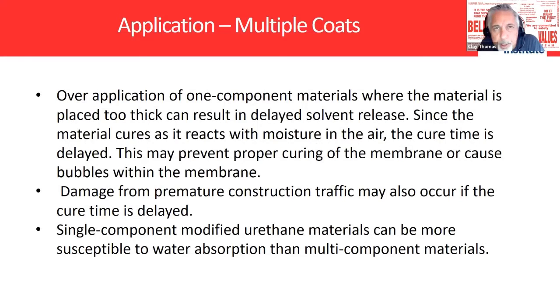And we used a mill gauge. A lot of times people think more is better, but you need to make sure that you're putting your applications of these products on at the correct mils, okay? You want to make sure you have the correct millage when you put it on so that it cures within the required time frame. Again, you want to be on a multi-employer job site. You want to make sure that your product doesn't get damaged by construction traffic. Single component modified urethanes are more susceptible to water absorption than multi-component materials.